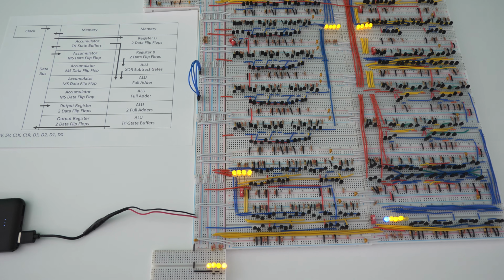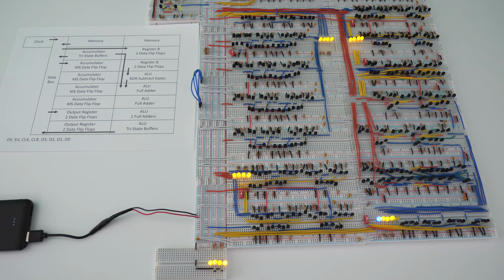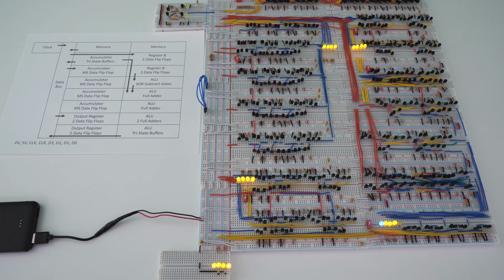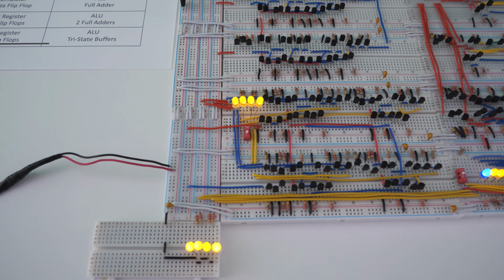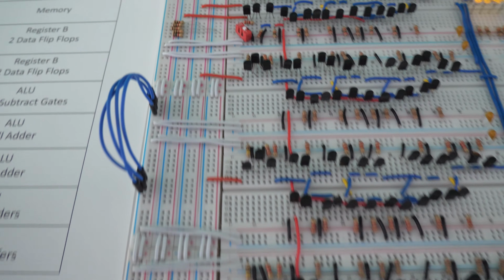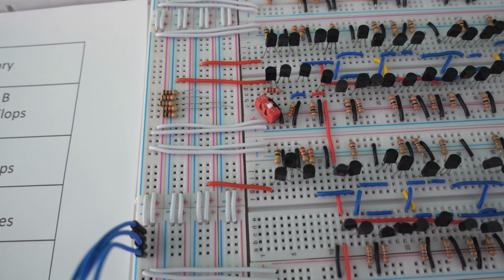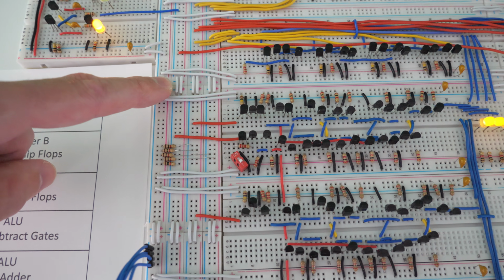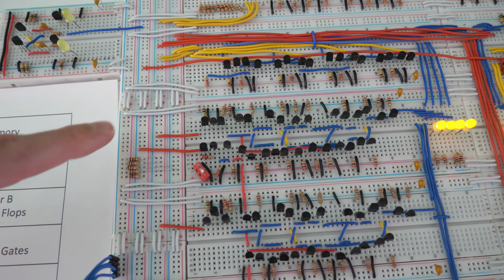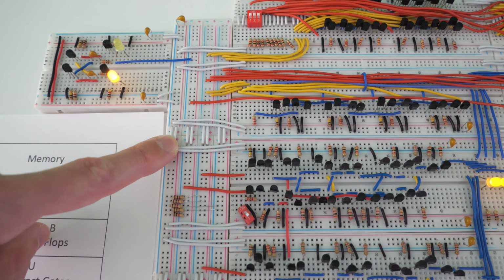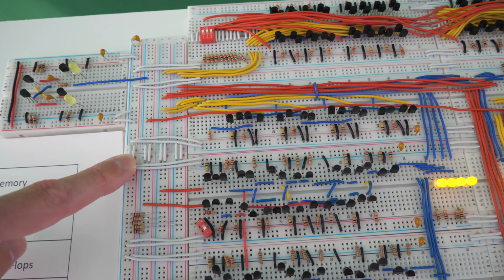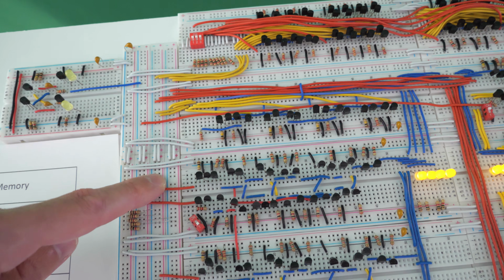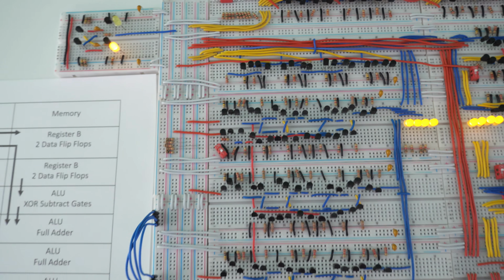And you might think that whenever you're actually sending information to the data bus, you would be sending a positive voltage. But what's actually happening is whenever you want to turn something off, you actually just provide a path to ground for these pull-up resistors, and then that makes the value on the data bus off. Also, if you look at the wire colors, white just means that power is going to be sent. So we distribute the power around the computer using the white wires, so you can pretty much just ignore those. If information is being sent to the data bus, the wire is usually yellow, and then if we're sending information from the data bus to the other registers, we will use a red wire.